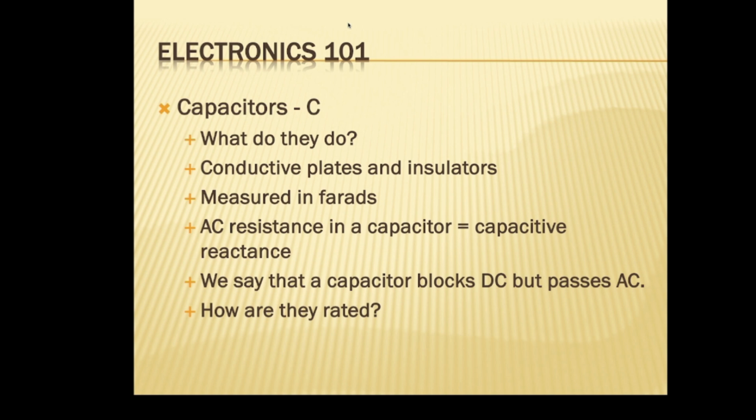0.1 microfarad, go to nanofarads. Now, I think we get a better reading as we keep going down. 10.9, so now it's 10.9 nanofarads, and you probably can go down one step still further. 11.01 nanofarads. Now, 2 nanofarads is going to be over range, so it won't go.